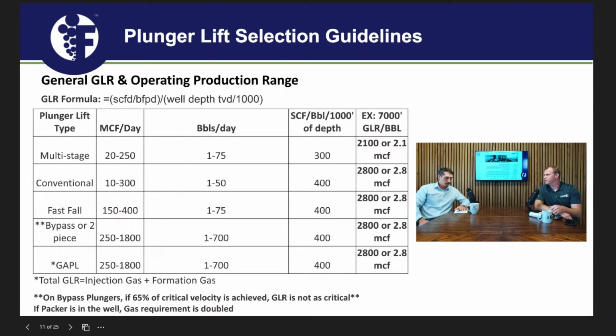And that makes sense because most Eagleford wells or conventional South Texas wells are going to be flowing in an annular mist flow regime to begin with. So you're going to have a lot of little droplets plus some kind of capillary flow of your fluids against the ID of your tubing walls, right?